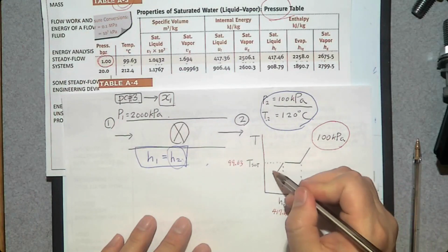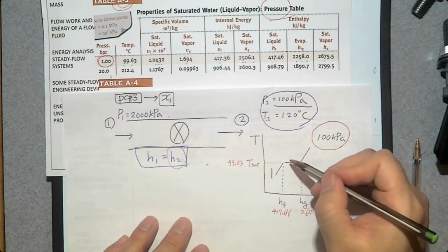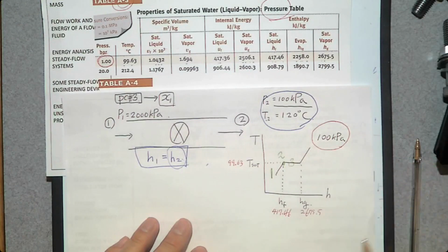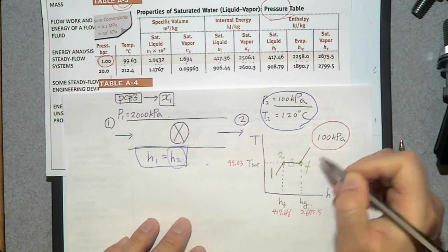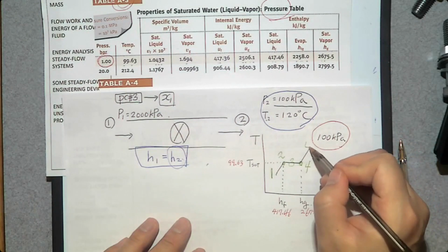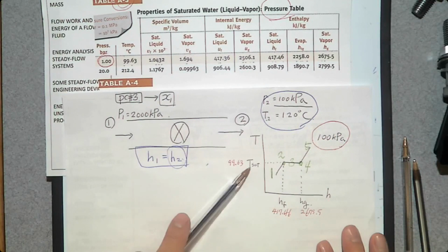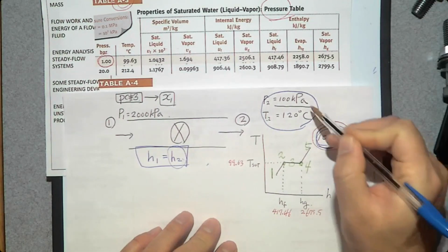On this T-h diagram, we have number one, compressed liquid here. Number two, saturated liquid here. Number three, saturated mixture. Number four, saturated vapor. And number five, superheated vapor. So now let's find the phase change process. How can we do that? We made this T-h diagram by using this pressure. So this one.